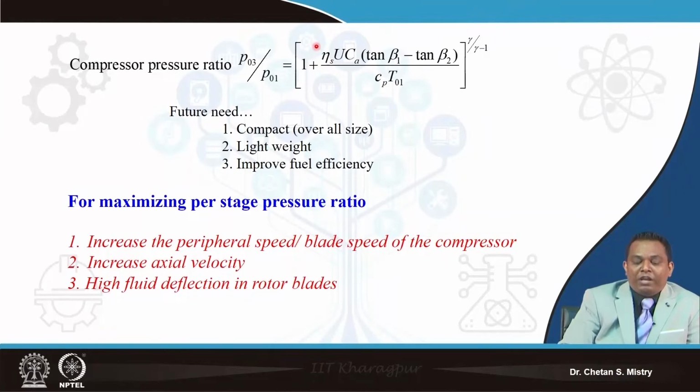Okay. Now if you look at here, this is what is representing my isentropic efficiency, my adiabatic efficiency, and we have realized that's what is basically depending on how many stages we are incorporating. Okay, and how good a design we are doing, because this is what is basically correlating losses. So if we are able to reduce the losses that are happening in my compressor, we can improve the efficiency.